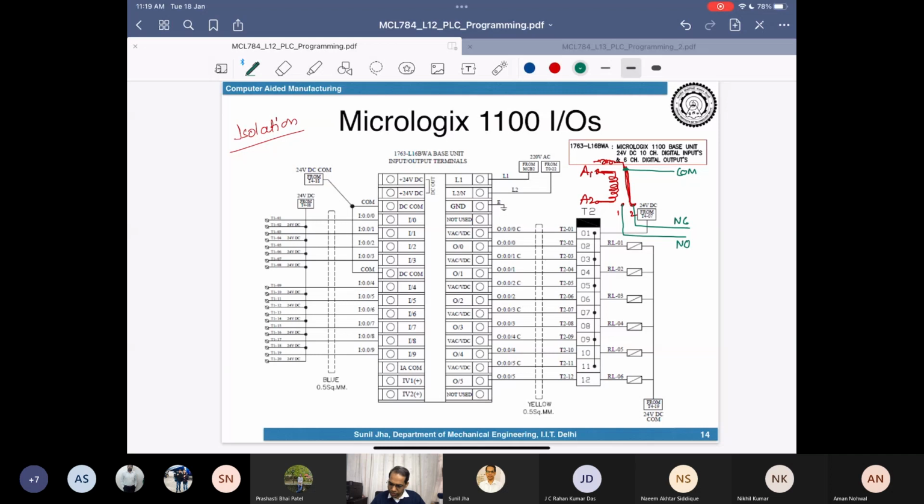And you can see that this A1, A2 is completely galvanically isolated. When we say galvanically isolated, it means there is no physical wire connecting the A1, A2 side of the circuit with the contact side of the circuit. It means the NO, NC, common have nothing to do with the electrical connection on the A1, A2 side. And this complete unit is housed inside a small box, and that is what we call the relay. Now let's try to understand the functionality over here. When the current is not flowing into A1, A2, it means that there is no current in the coil.